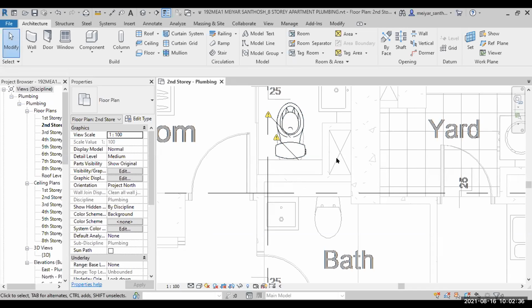So in other words, here the outlet should have one water pipe, then with a gate valve. Then the piping is a flex pipe to connect to underneath. So you can modify this to below the base of the WC. So all this can be configured.